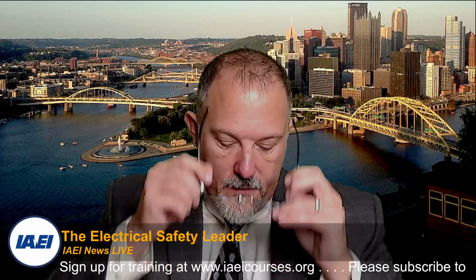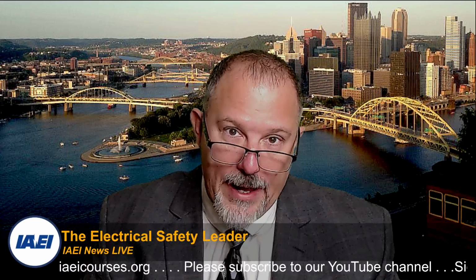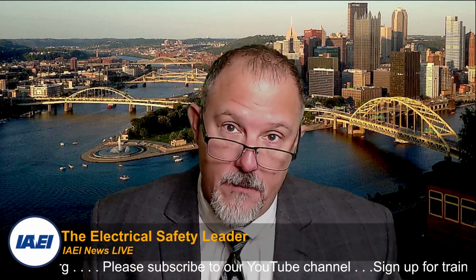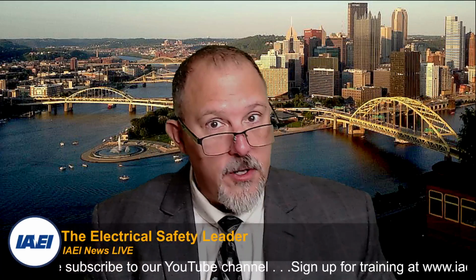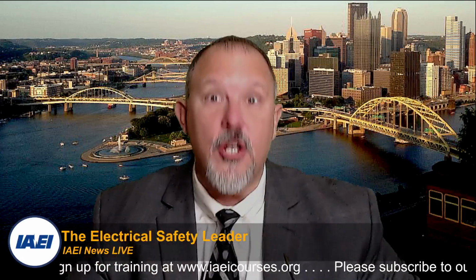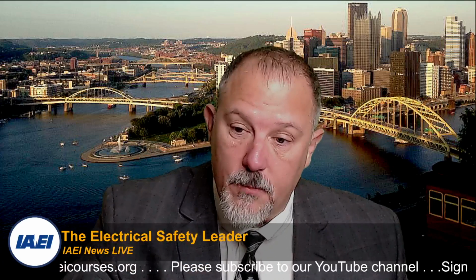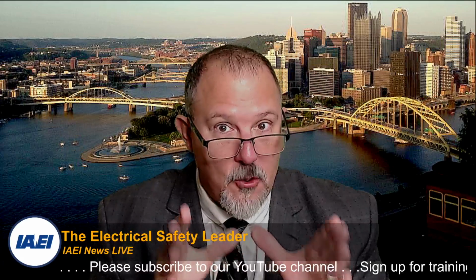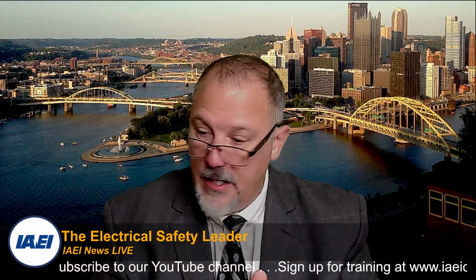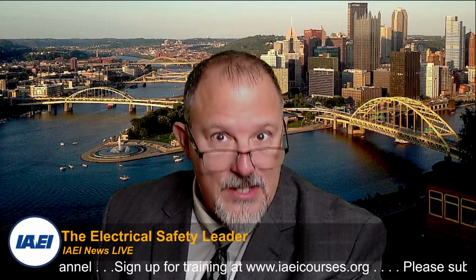Why? Because I have to understand the concept of inverse time as the qualifying term for a circuit breaker. Inverse time means lower currents can produce longer clearing times. Lower currents, longer clearing times. Longer clearing times on arcing currents produce higher incident energy. This is why we're talking about the fundamentals of circuit breakers here, because this is a very fundamental principle that's important to understand, especially when we're trying to understand more complicated concepts such as incident energy.